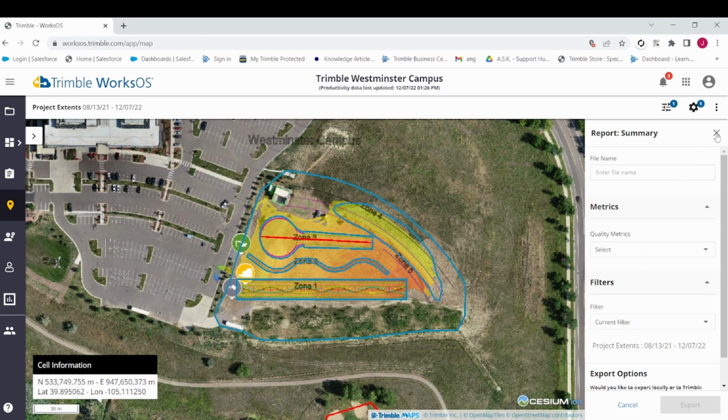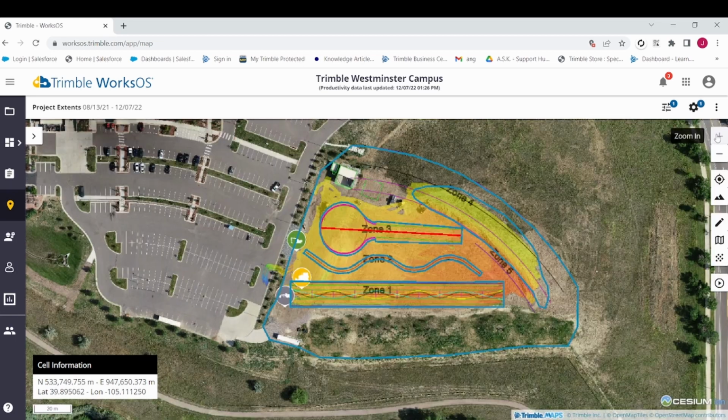Another thing to remember is when you are in excluded elevations, the export and report options will only pass the excluded elevation data. When you're not viewing excluded elevations, the export and report options will pass the elevation data, not including the excluded elevations. Be careful to be in the right mode when you are filtering your data by elevation range. So that's just ensuring that your excluded elevations is turned on or off when viewing data.